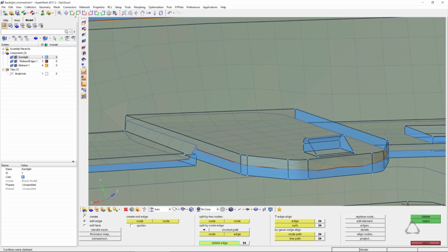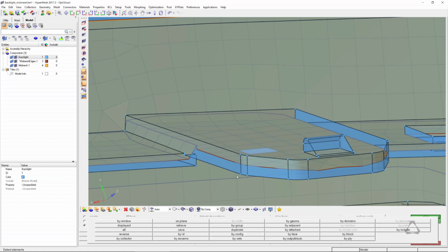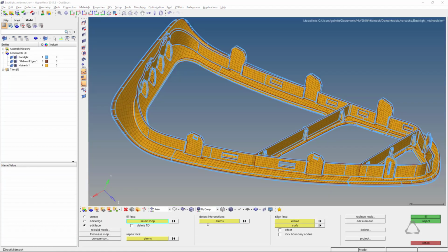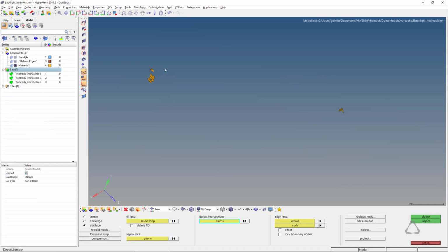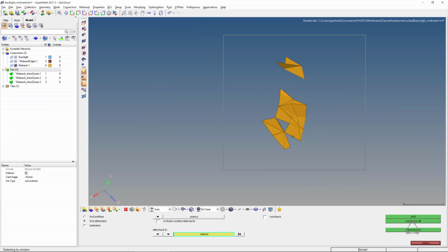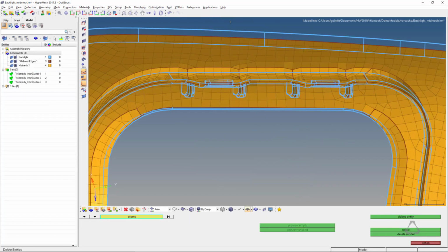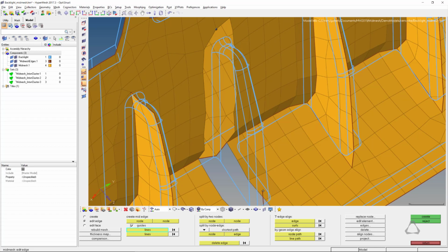Here an unnecessary edge is removed and the elements smoothened to better represent the geometry. Problematic areas can be quickly identified by the Detect Intersections functionality. It generates sets which can be isolated and further investigated. In some cases, deleting the elements and rebuilding the area works best. In this case, a new edge between specified lines is generated.